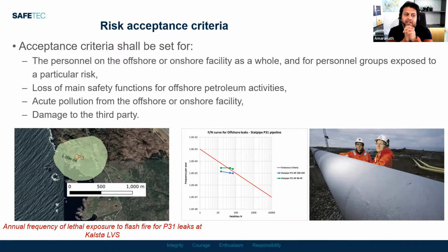In the risk analysis, there are different ways of calculating consequences due to releases from, for example, buried pipe sections. It won't be like a free flow jet. It will be more like a diffusive fire if you have a leak from the buried pipeline.